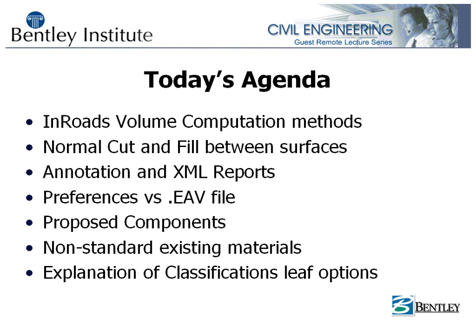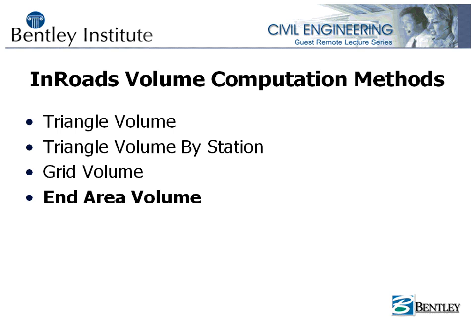We're going to look at how to incorporate proposed components from our design surface into our cut and fill volumes. We're also going to look at how to incorporate non-standard existing materials into our cut and fill volumes. And finally, we want to look at the classifications leaf of the end area volume tool in a little extra detail.